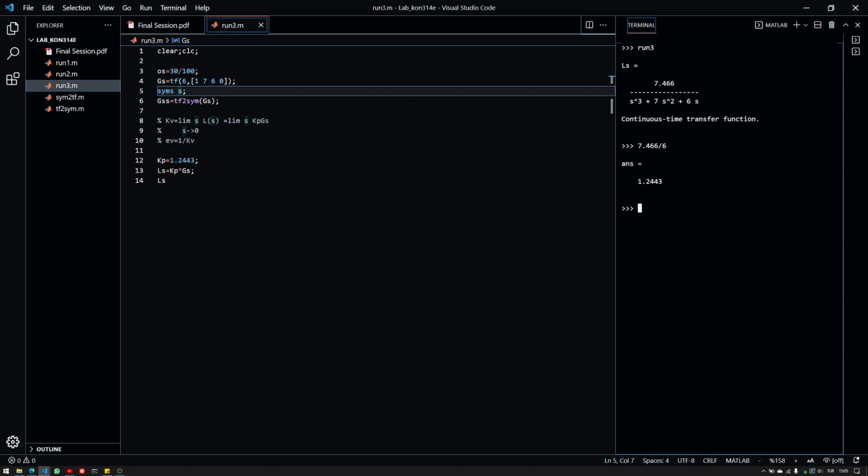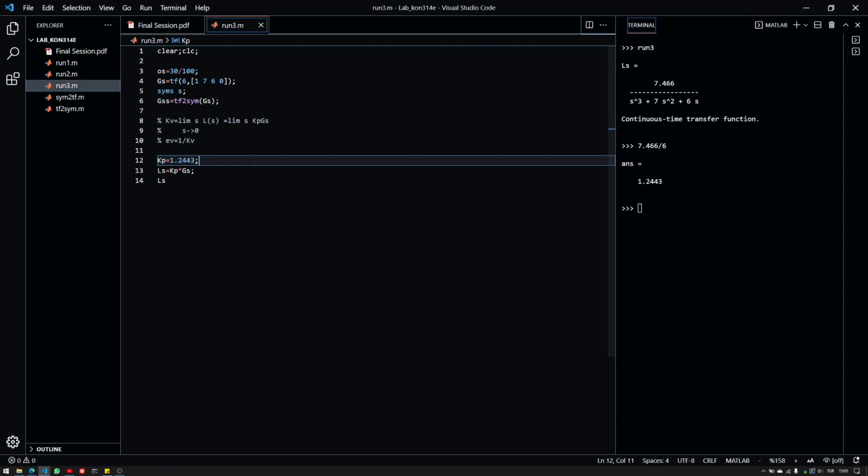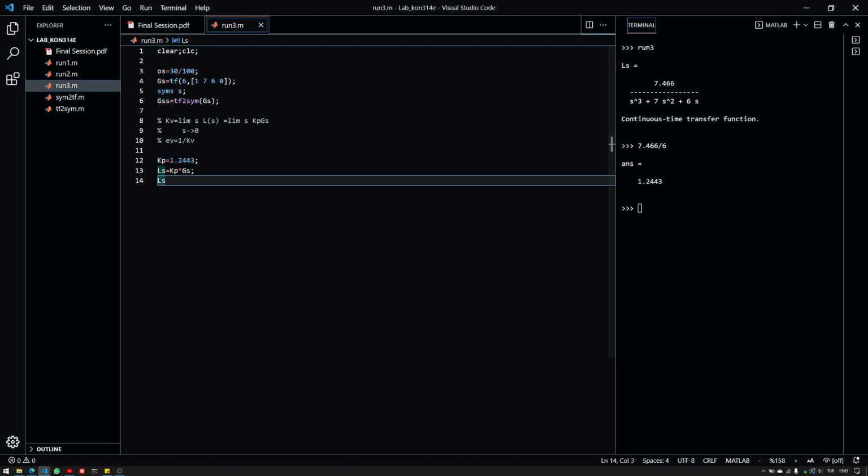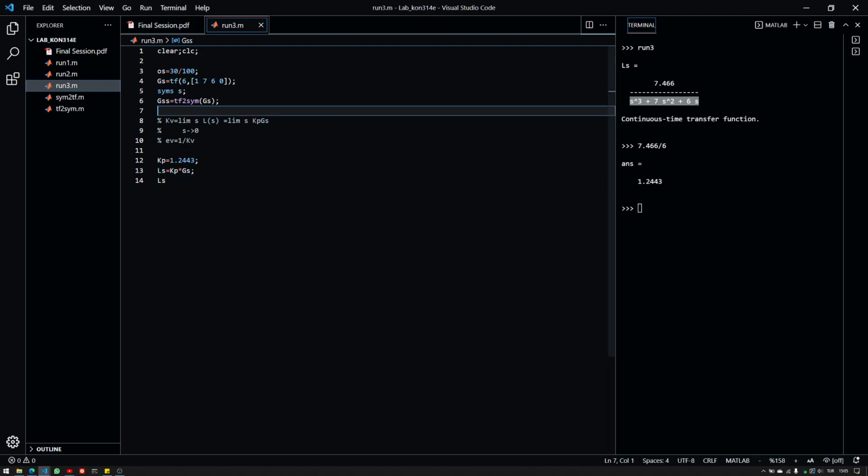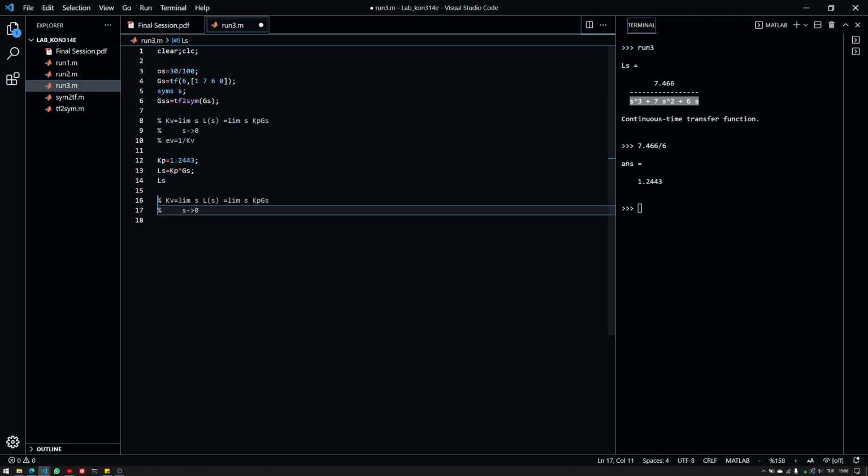And you can also see that this is basically the p-type controller that we have here. So usually for the position constant, we use directly s equals 0. Now for this, we can see that plugging s equals 0, or taking this limit here. So let me copy this, and let's see what happens. So we have the position constant, we don't have this s, and plugging in this here, looking for this limit here, results in infinity.